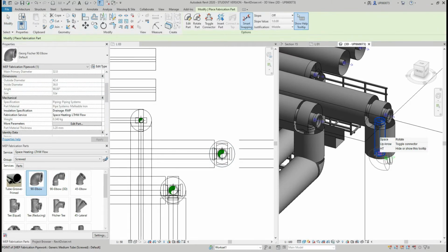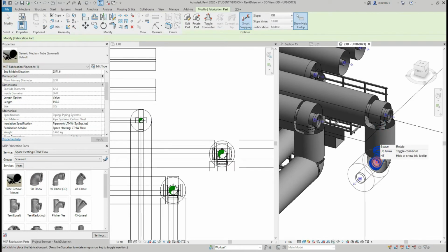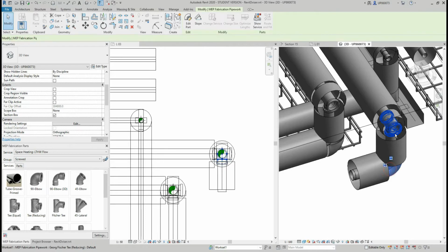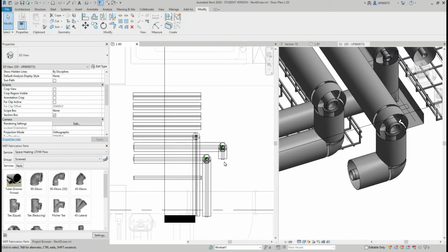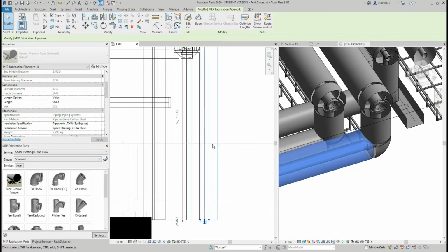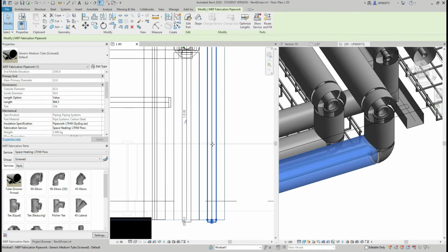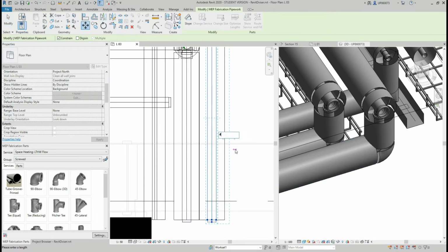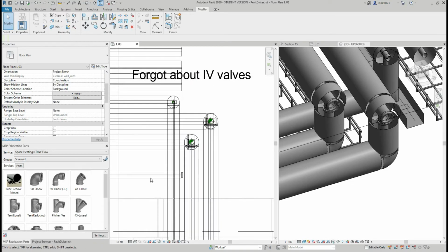Find elbow. Create similar. Make sure that the insulation is the correct one, LTHW. Again, stretch the pipe. Make sure that it's 40 mil away from the insulation. 40 mil between insulations. And finally, I need to model sprinkler.